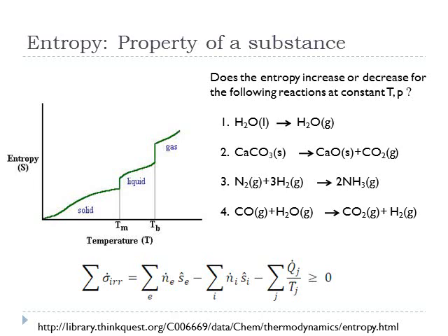So we're going to look at these cases where the box is kept at a constant temperature and pressure, but we have a system that's flowing in with, let's say, liquid water at first, and it's leaving as a gas. Okay, so a couple of things we can say about this, right? We know that there's an increase in the entropy. If we look down at this equation at the bottom, what I've done is I've taken the second law balance equation and rearranged it, and the internal irreversibility occurring has to be greater than or equal to 0.